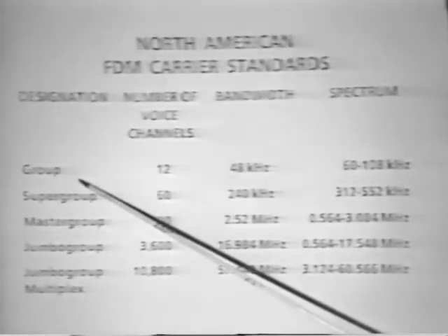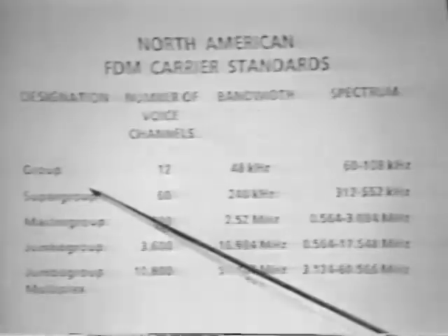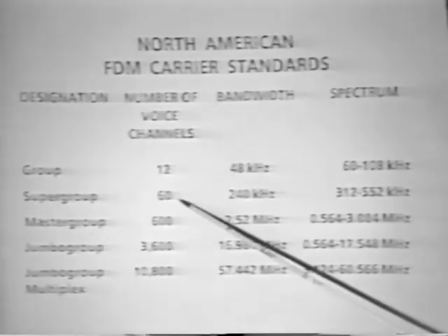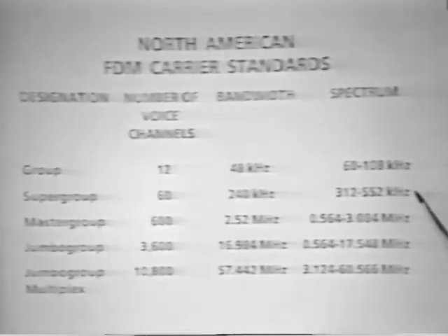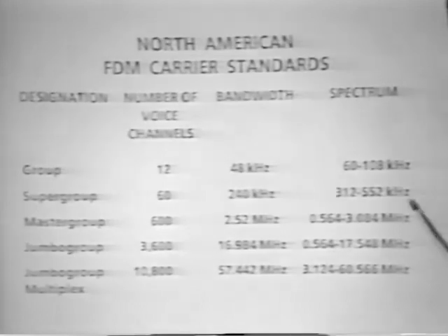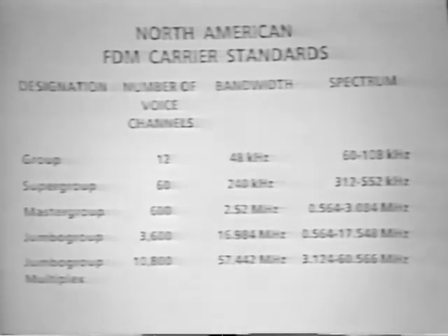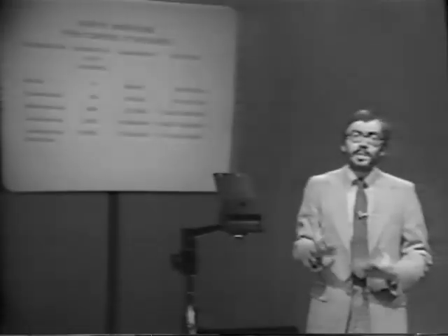If you want to send data over a relatively low capacity line, like a twisted pair line, you would multiplex either at a group or supergroup level and send those voice signals out over the line. If later on that twisted pair line feeds into a coaxial cable transmitter, you can add that group to other groupings and get more voice channels on the same physical link. So the point of these standards is just so that it is easier to make the intermediate equipment where the multiplexing and the demultiplexing takes place. And they're just standard groups of channels that are used.